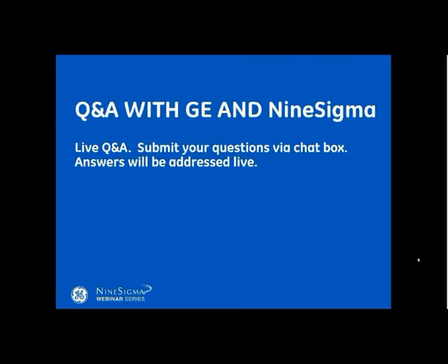Yes, I will. So we're trying to replace the interconnector, and so the small 5-inch long, 1-inch diameter piece of plastic with the 2 O-ring grooves, that is what we refer to as the interconnector. That's our standard industry term for it. We're actually trying to remove that piece and remove the 4 O-rings and incorporate the connection into the central tubes that are part of the 40-inch long module. So it's not necessarily to connect between the interconnector and the central tube, but to actually replace the interconnector and connect from one central tube to the other central tube.